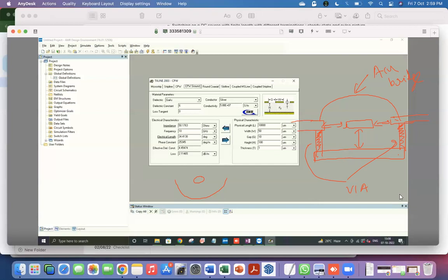It's not as simple as that, because the width part of the transmission line, if the bottom ground plane was not there, there are field lines going both above and below, right? And in fact, the field lines will predominantly go below, into the dielectric, because that's where the field lines can penetrate a lot easier. But it's not like a simple parallel plate capacitor, and the air also plays a role. So obviously this dimension will have a dominant effect.